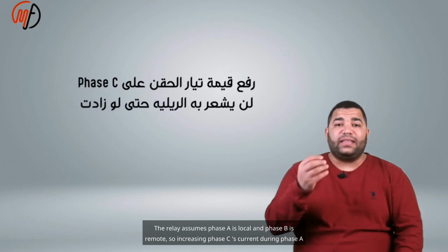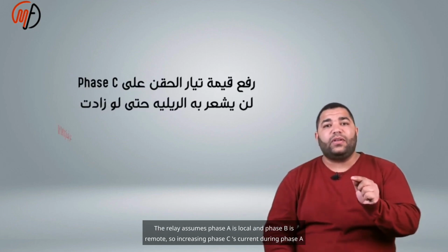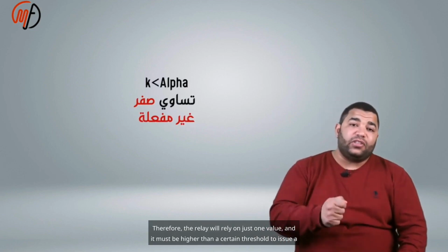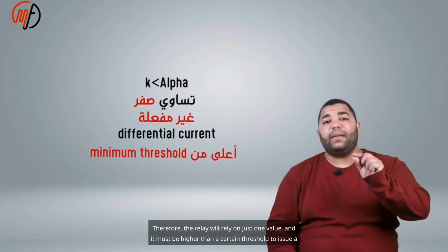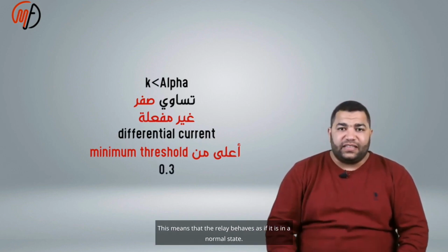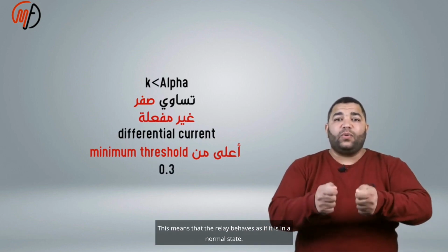The relay assumes phase A is local and phase B is remote, so increasing phase C's current during phase A testing won't be detected even with higher injection. If K at angle alpha is 0, it's inactive. Therefore, the relay will rely on just one value, and it must be higher than a certain threshold to issue a trip signal. This means that the relay behaves as if it is in a normal state.